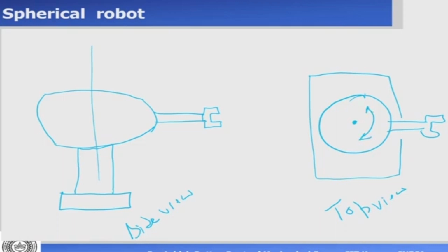So there is a theta 1 there. Next, the axis is coming out of the plane, if you can imagine this, so it can rotate about this axis. Here there is a rotation joint, so there's another theta 2. And this is a translating joint, which can go up and back and front like that. So that's theta 1, theta 2, and d3.